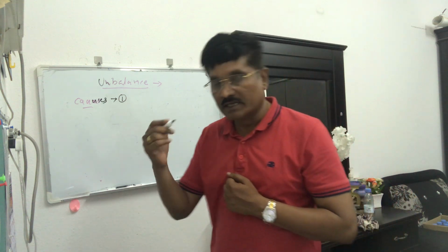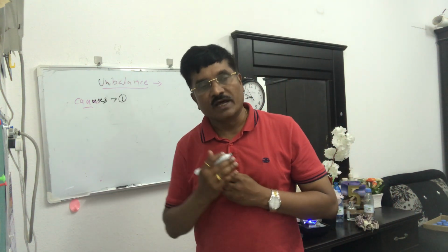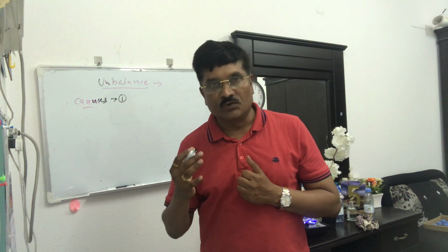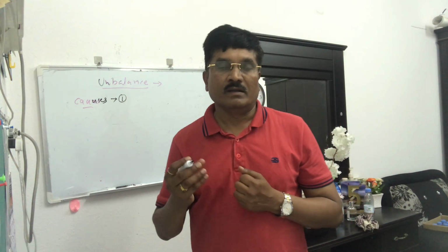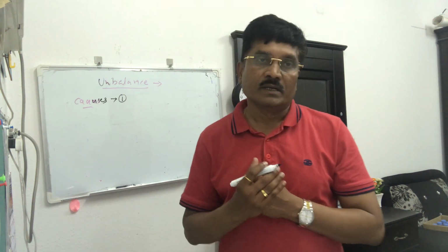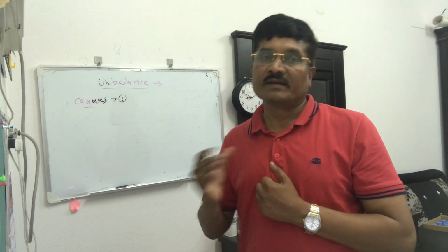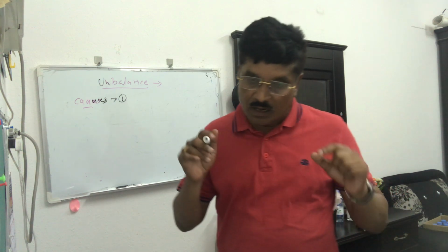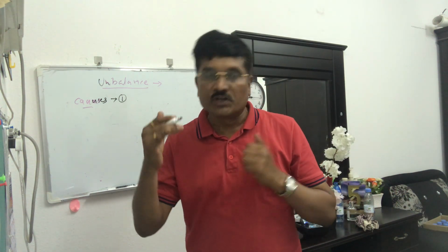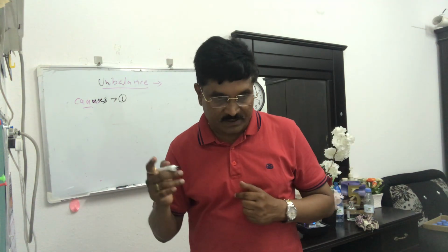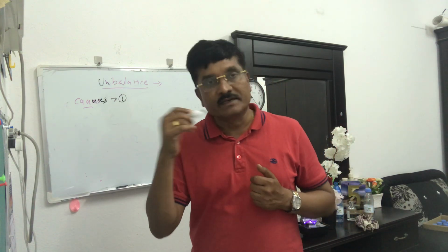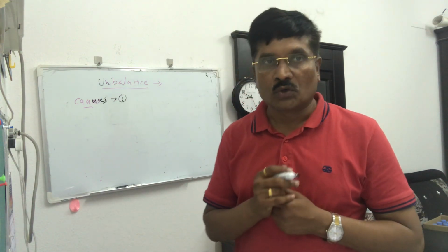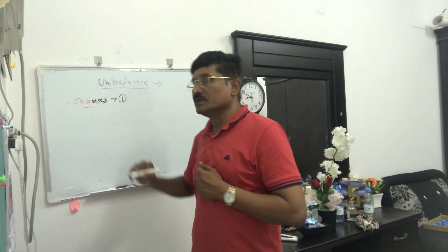Second thing is while running the machine along the period of life, it creates unbalance itself due to wear and tear or missing of some rotary part, damage of any rotary part, or deposition of the material, welding of the material along the rotor. It also creates unbalance while running. Third thing is porosity or uneven build up of the material, non-symmetrical condition like motor winding. If it is not proper, then it creates unbalance in a motor rotor. These are some of the causes of the unbalance.